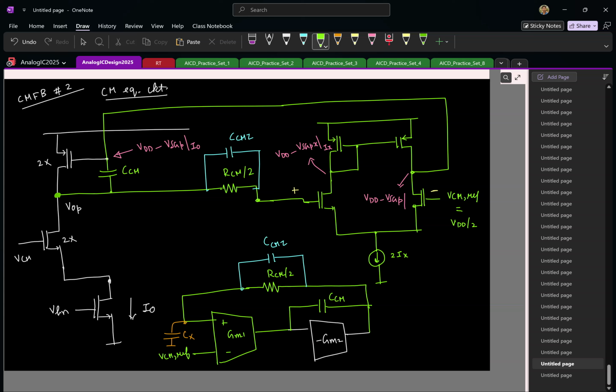Correct. So as you see clearly, if I have an NMOS input pair, the voltage here is naturally at a value that is compatible with the second stage. This is something we saw in a 2-stage OTA, right? If your input pair is PMOS, you are better off with the second stage being NMOS. Vice versa, if the second stage is PMOS, a better option is to have an NMOS as the first stage. Same thing.